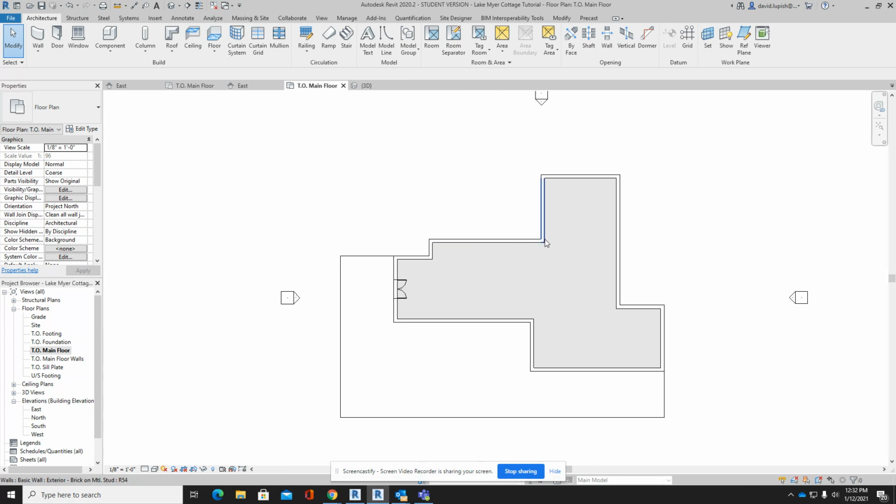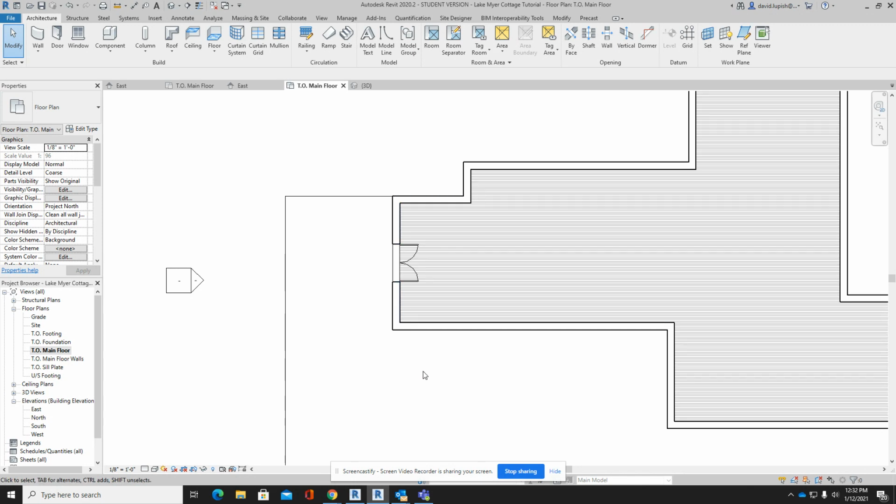Essentially, depending on what type of exterior finish you have for your building, the position of the sill plate is going to be different on the foundation wall depending on your details. So if I have a building that has siding, for instance, that sill plate will be installed to the outside edge of my foundation wall.